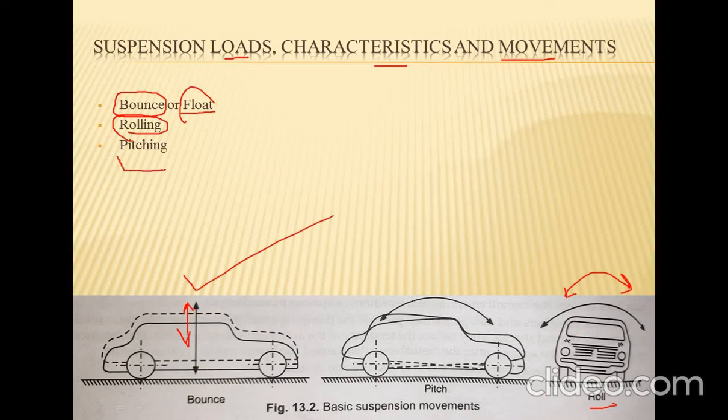So next is the pitch. So the pitching is mentioned here in this diagram. You observe the movement of the car. Pitching is the rocking chair or rotating movement of the vehicle about the transverse axis. When brakes are applied, there is weight transfer from rear axle to front axle. So you observe when brakes are applied, this moment of rear axle just goes to the front axle, that causes the nose of the vehicle to dip, to be lowered.